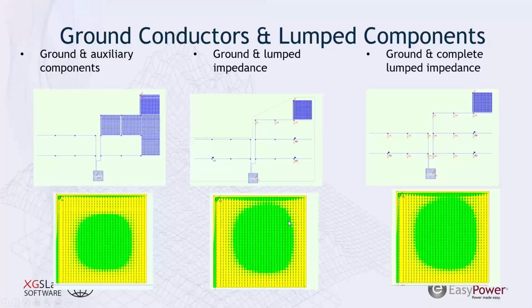Part of that can be artificial because we are making this connection and indicating that that is to remote Earth, and that's just a parallel impedance to our system, and it doesn't produce the ground potential rise that you're going to see from these that might affect this system performance. So that's something to consider in that modeling.